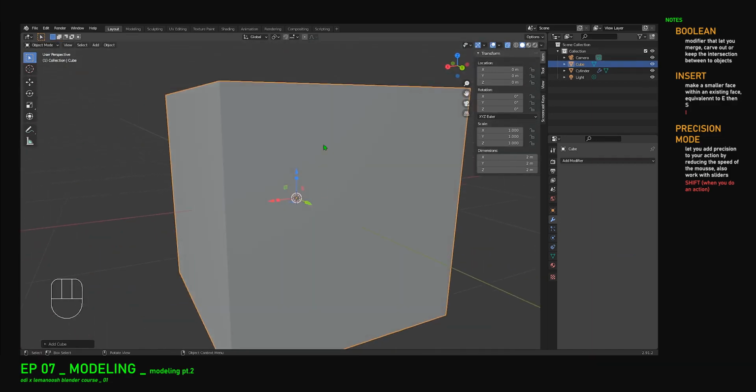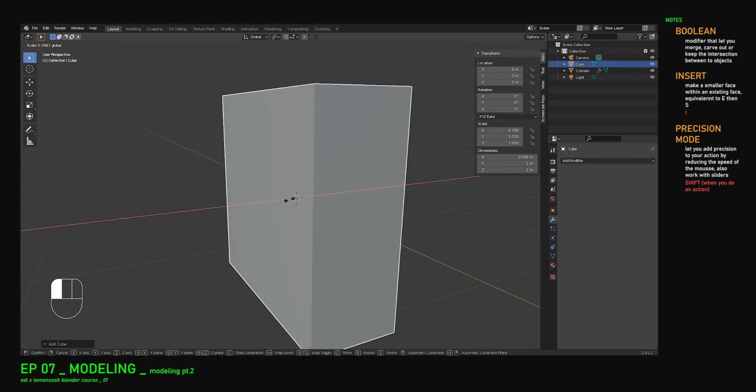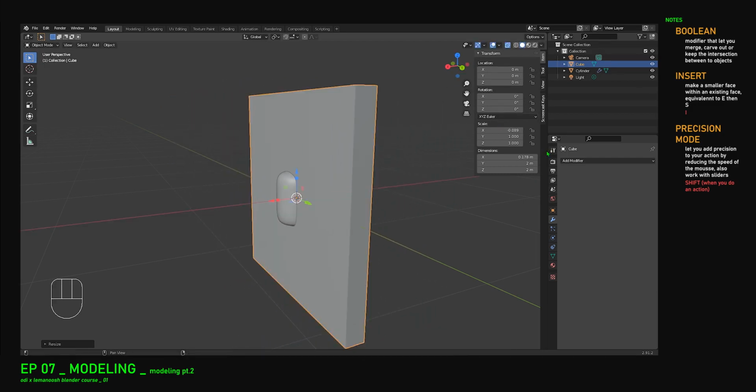Also here we want to make the cube way thinner so that it just looks like one rib, and we could do that by just scaling it here. The thing though is that then the properties of the scale here will not be 1, and you will see later on that you want those to always be super simple. So most of the time you want your location to be 0 everywhere, same for the rotation and same for the scale.